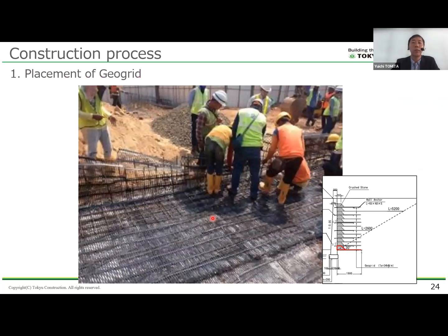For the 3RGRS retaining wall, Japanese engineers provided technical guidance and on-site training to the local staff. This helped ensure that proper construction procedures were followed and the required quality was maintained. Geogrid reinforcement is installed at the heights, orientations, and lengths specified in the design. Standard length layers are placed every 30 centimeters of compacted backfill, and longer layers are added every 1.5 meters of height. The backfill surface is carefully leveled to avoid any unevenness, so that horizontal tensile forces are distributed evenly across the geogrid.